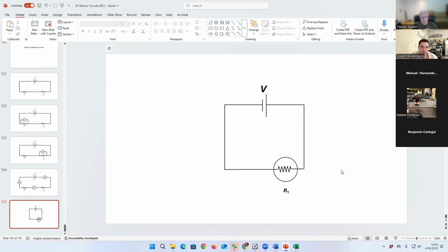Okay, so if somehow the vacuum inside the lamp is not as perfect, then air is going to seep into the bulb, right? And the oxygen is going to start oxidizing the resistor. And when you start oxidizing the resistor, it is going to become very brittle and it's going to break because of the oxidation, okay? That's why they have to keep that resistance there in almost vacuum. That's for incandescent light bulbs, right? For the other types of light bulbs it is different.